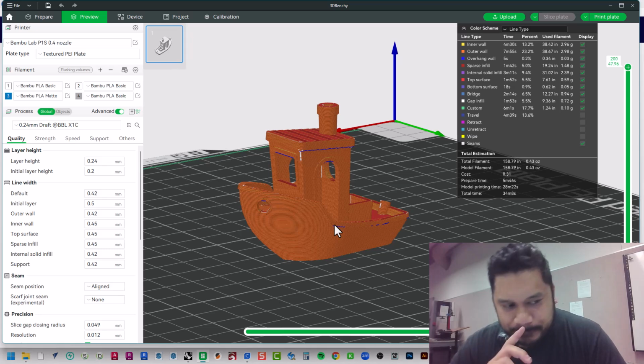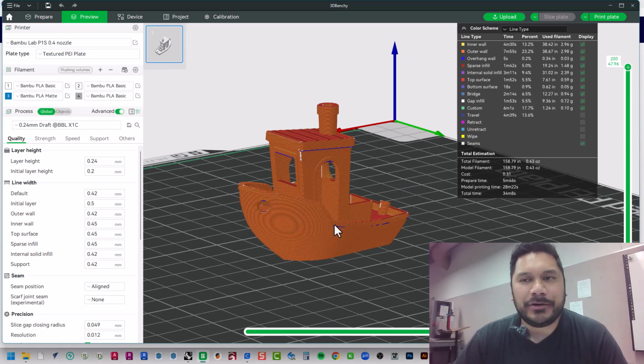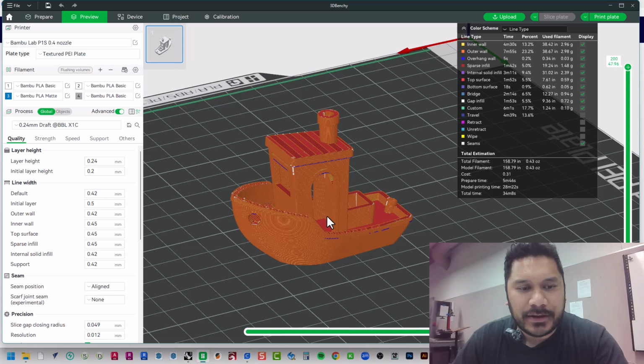So what are we going to do here? The next step after 3D modeling in Rhino is to slice our files. Slicing is the process of converting a 3D model into layers that a 3D printer can understand. The slicer software takes the geometry of the object and generates a toolpath, basically instructions for the printer's nozzle on how to move and extrude material by layer.